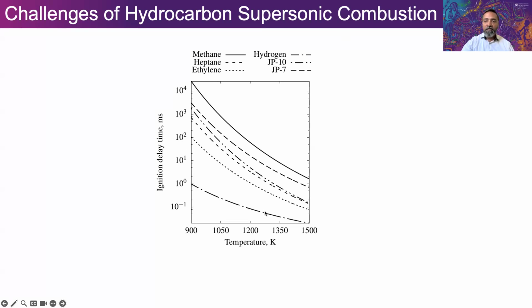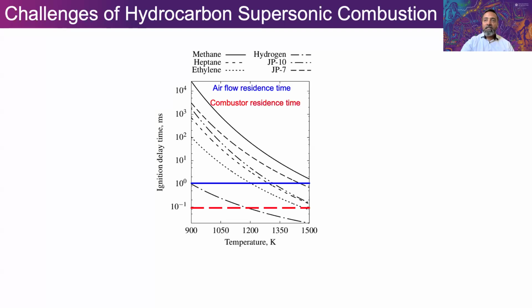It's a beautiful fuel in terms of combustion. No problems burning hydrogen in almost any vehicle, but all the problems start occurring when you look at hydrocarbon fuels. Now, to contextualize this a little bit more, the air comes in at 2 kilometers a second outside, rushes through, and you can see here, it spends about a millisecond within the entire engine, from where it enters to where it exits. And now if we narrow down on how much time it is spending in the combustor, which is where we hope to mix fuel and burn, it's a fraction of that time. So that makes the challenge even more difficult.